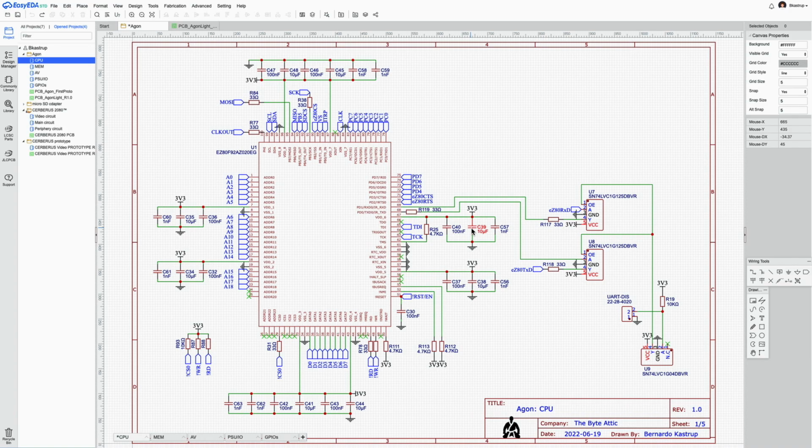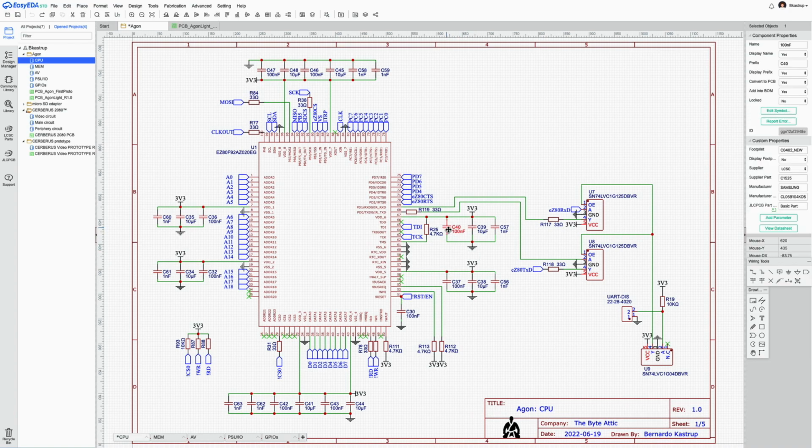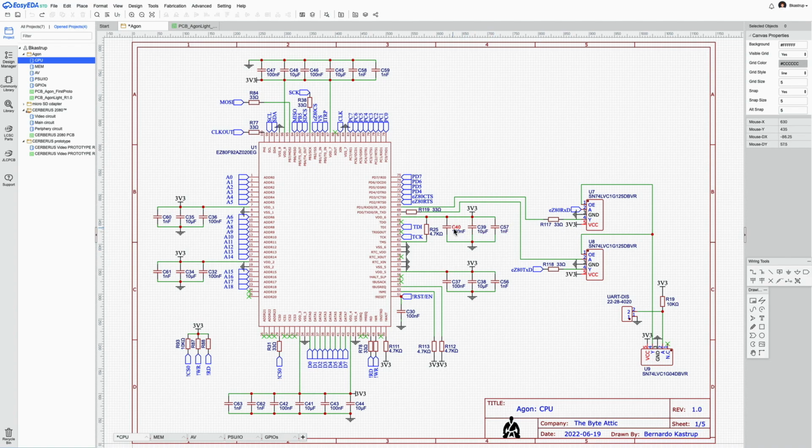So you don't need to use multiple, you just need to calculate the right value given the resonant frequencies of the power distribution network. Well, the problem is it's a pain in the neck to calculate that or to use expensive tools to simulate and give you that value. So I didn't want to do it. I just preferred to cover an entire range of frequencies by putting several, or 3 in this case, values on every VDD or VCC input of the chip as bypass. So I was just being lazy.